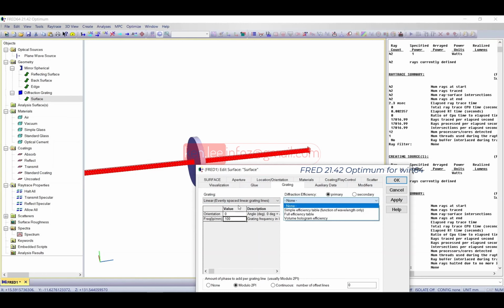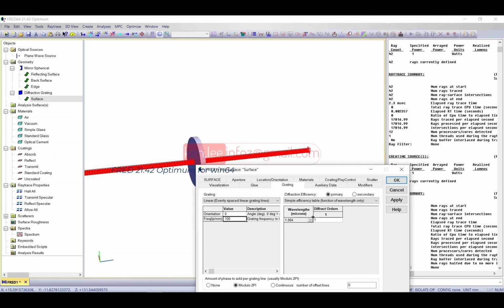And what we'll also have to do is define the diffraction efficiency. So how does the program know where the power goes to, which diffraction orders, what you would like to simulate here. You will have to tell the program. If you just specify one wavelength, then it will be all the same. So for all the other wavelengths, you will get the same diffraction efficiency. You can add other wavelengths here. So you can put other wavelengths and give them a diffraction efficiency, but we won't do that.